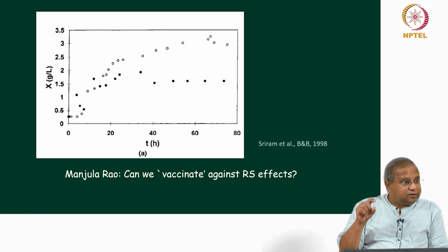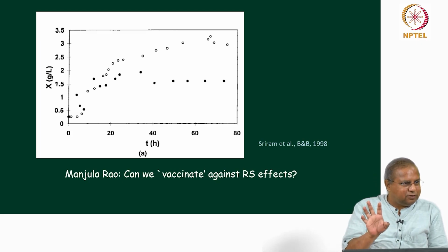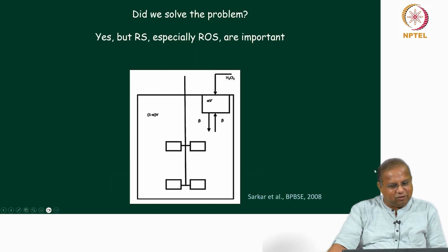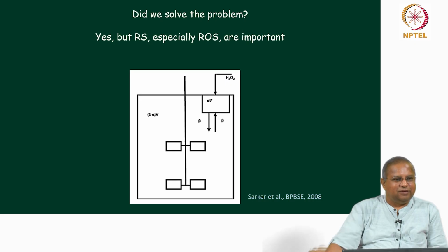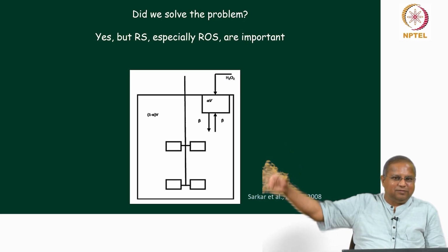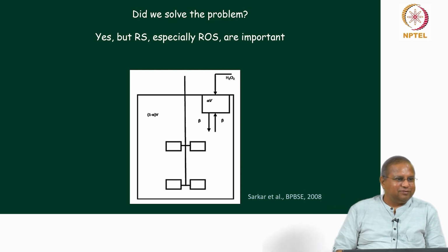Yeah, no, it's a concentrated solution. The required H2O2 is provided, only in a lower volume, but it will cause difficulties like this. The concentration here in the feed zone will be very high, so the toxicity will be high. Is there any other way of adding it where it's not concentrated? Yeah, various things. You could generate it separately and add it, and so on. So a lot of these thoughts.